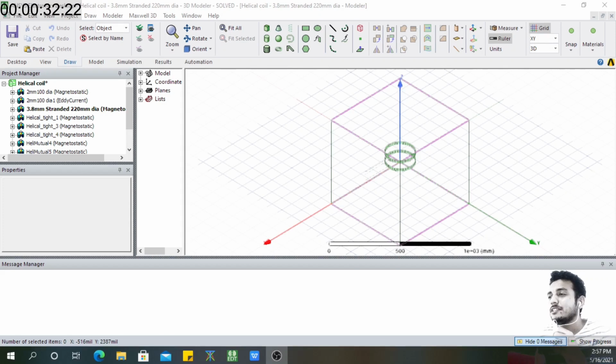So previously, we calculated inductance values, and the matrix was created by the simulation. The matrix was created for the distance sweep between the TX and RX coil, and the self-inductance value was calculated, right? So mutual inductance and self-inductance, we had this data. What we will do now is put that matrix in the form of a block that can be used in a circuit diagram.